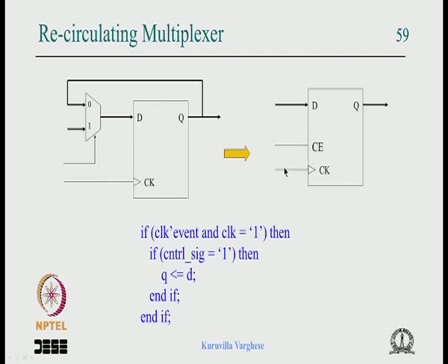Otherwise a 4 input lookup table will be wasted on 3 input logic, because a 2-to-1 mux has 2 inputs and 1 select line as input. So it's a 3 input logic, but a 4 input lookup table will be used to implement that.